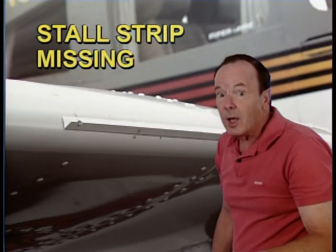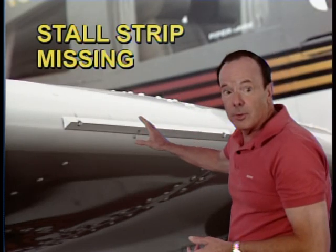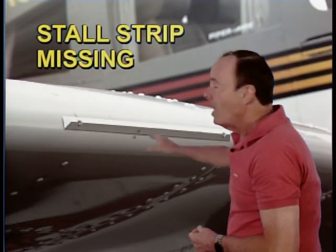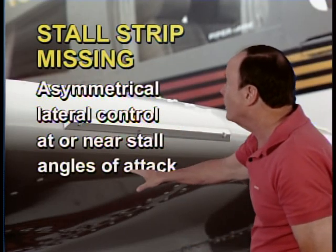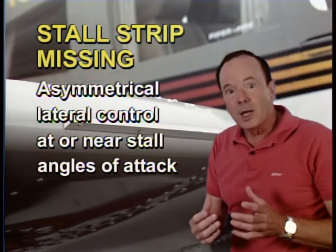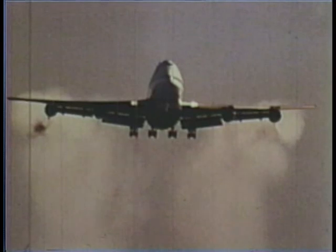And at very high angles of attack, you might have more lift on one side of the wing than the other. And the aileron on one side would be more effective than on the other. And they call that asymmetrical lateral control, and it occurs at or near stall angles of attack when a stall strip is missing. Now let's take a look at a wing generating lift, and this is a magnificent Boeing 747 with smoke generators on the wingtips to show you what's happening to the air around the wingtips.